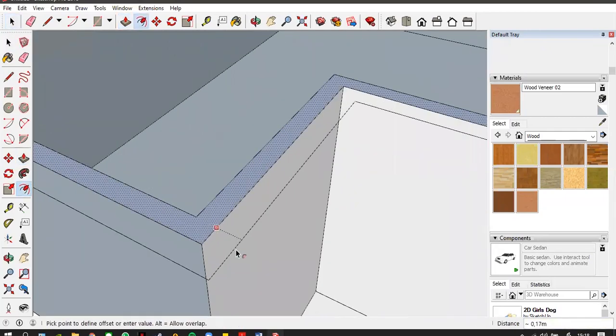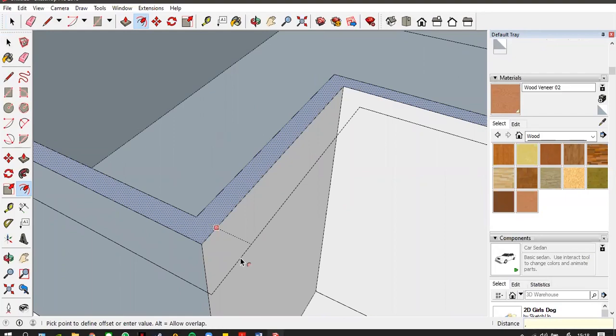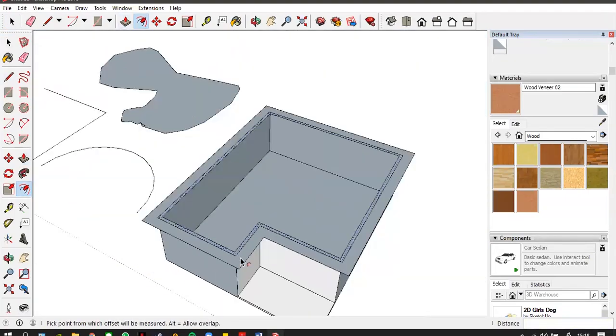Offset the top surface of the wall to create the roof. Let's assume the overhang of the roof is 50 centimeters wide. Then create the roof by creating 2 triangular prisms, the large one for the main roof and the smaller one for the front area. We start by making the main roof. We assume the roof is 2 meters high.